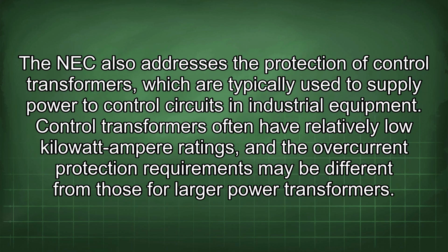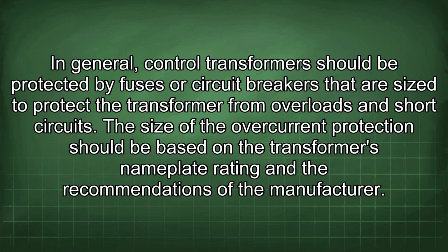The NEC also addresses the protection of control transformers, which are typically used to supply power to control circuits in industrial equipment. Control transformers often have relatively low kilovolt-ampere ratings, and the overcurrent protection requirements may be different from those for larger power transformers. In general, control transformers should be protected by fuses or circuit breakers that are sized to protect the transformer from overloads and short circuits.